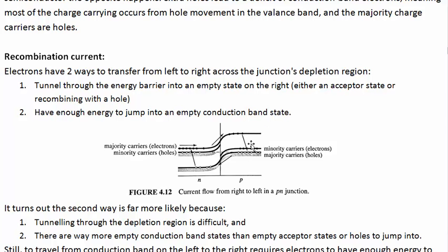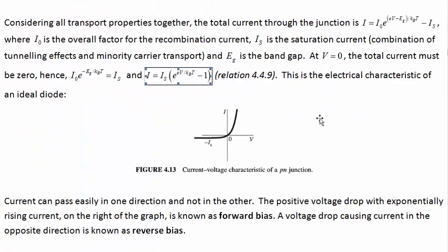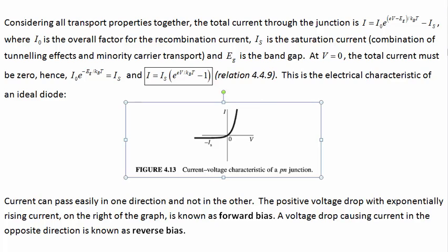If the voltage is applied in the opposite direction, so that we raise this barrier, then conduction can't take place very easily, because sure, if there were electrons here in the minority carriers, they would be able to jump across, but there's so few minority carriers on each side because of the doping that's not a big contribution to conduction. Similarly, the tunneling effects can still happen, but those are quite a lot smaller than the kind of current you could get in forward bias. Overall, the diode behaves like this, and gives you a current profile that looks like that.